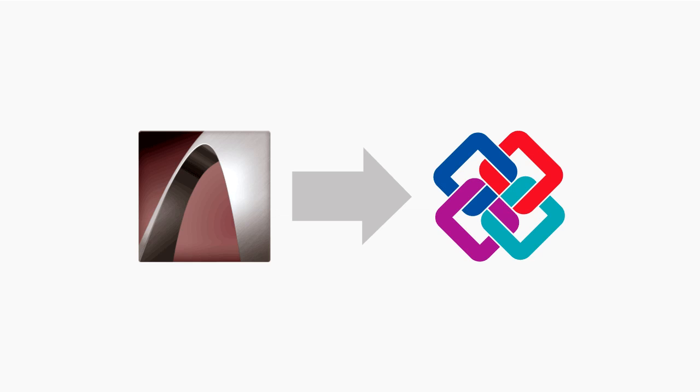You can save ArchiCAD data as a specific IFC model to match a particular standard, like COBie documentation or your company's standard. Or you can make your data fit a particular workflow, like MEP or energy analysis. Or you can optimize model data for a particular receiving application like Revit or Tekla.